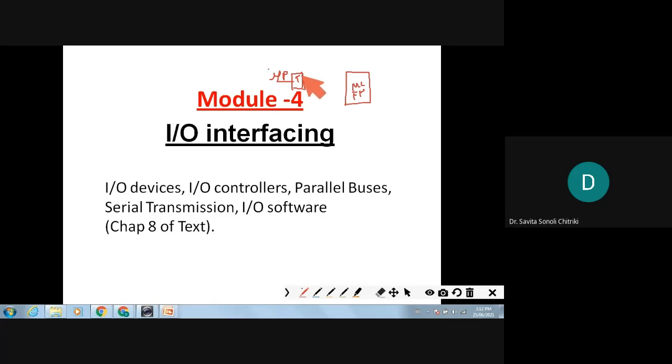Then next, you can directly connect if it is generating a digital output. But if it is generating an analog, then in between you need a signal processing circuit, that is analog to digital converter. So that digital data is fed to the microcontroller here. Like you can think, we had done one container example where we were monitoring the level and temperature. So level and temperature were monitored. All right. So if it is an analog signal, then we need A to D.